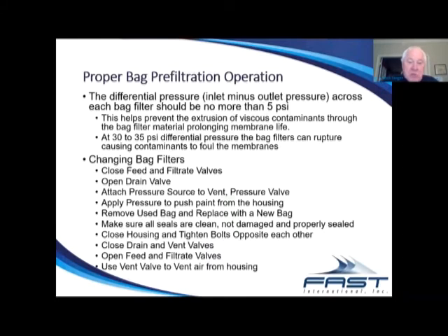So you took all the dirt that was in the paint in the bag and dumped it back into the clean side of the bag filter, contaminated the system. By the way, that plugged up the ultrafiltration housings very quickly.